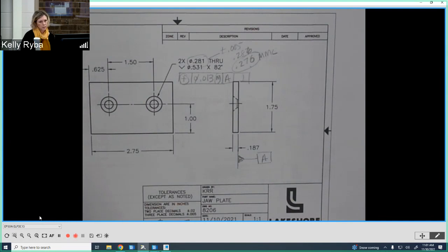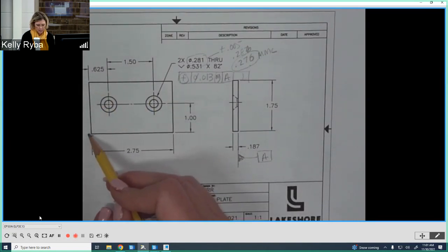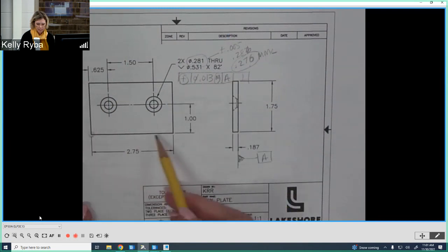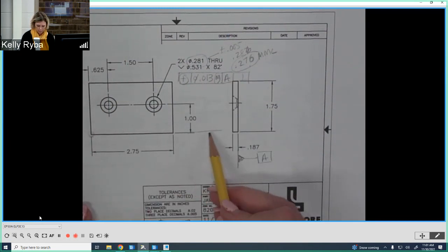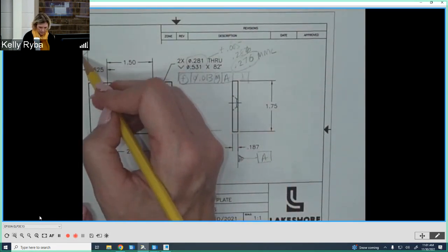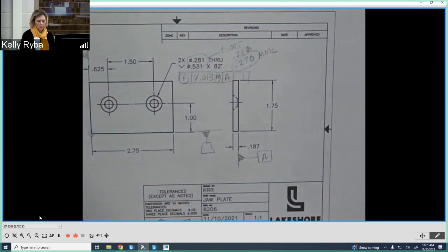And then we have to look at our dimensioning scheme. Where are we dimensioning from? It looks like we're from the bottom and then over from this corner. So this is our 0, 0, if you would. So that means that this bottom surface right here would be a datum. And this side surface is going to be my other datum. And again, this isn't super critical as far as surface finishes, because again, we're in a machinist vice.